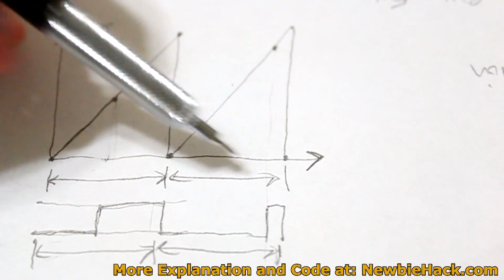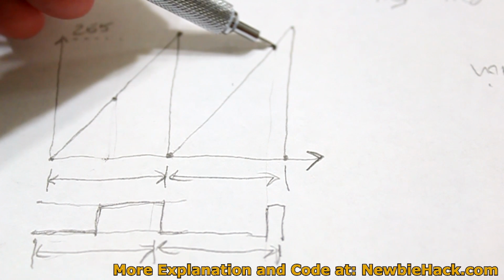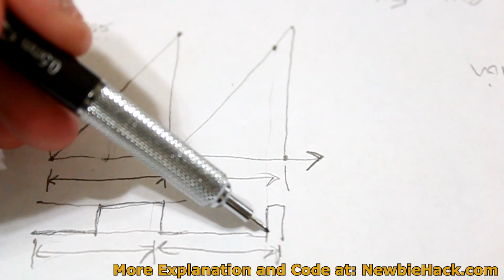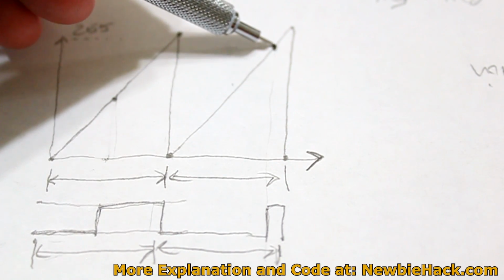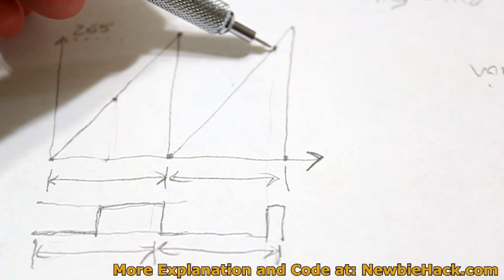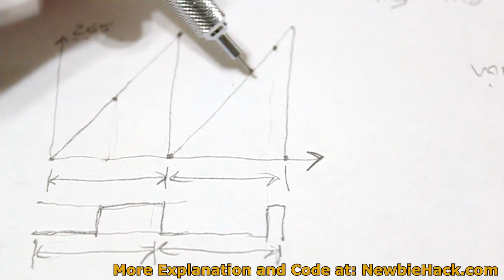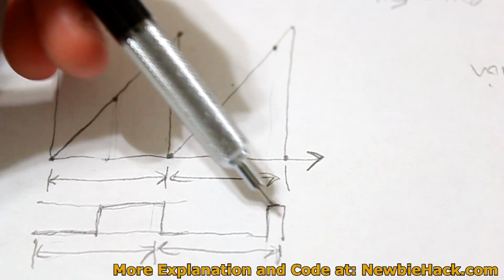So just by modifying the number at which the timer will produce a signal of 5 volts is where you're going to have your pulse. That's really simple. When the timer gets to whatever number you want, you can have this pulse outputting to any pin that you would like.